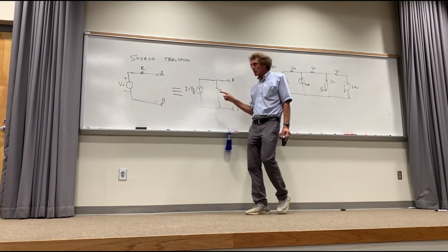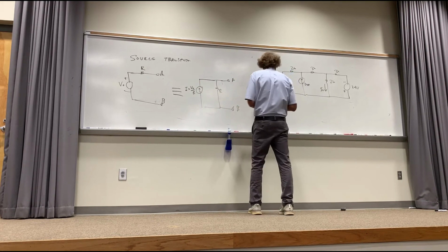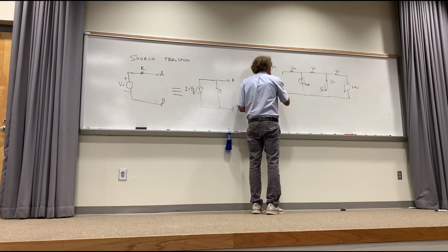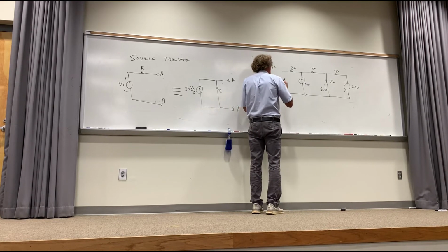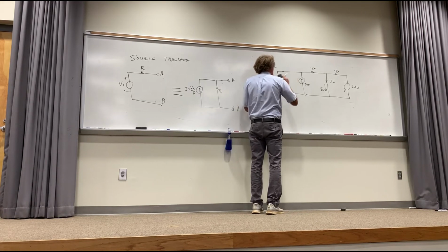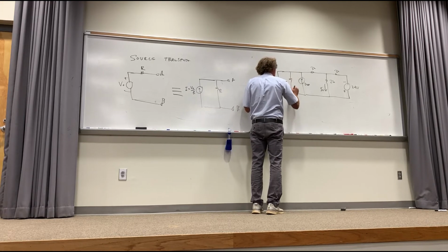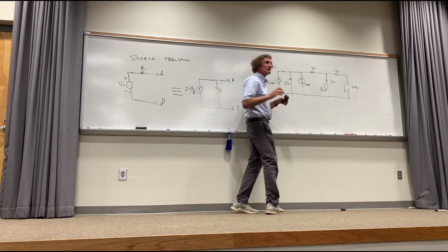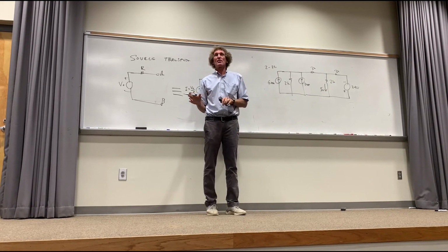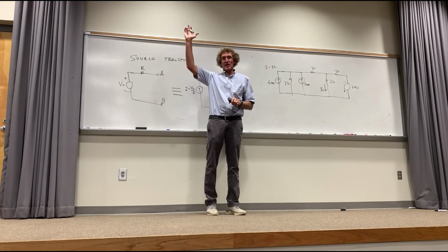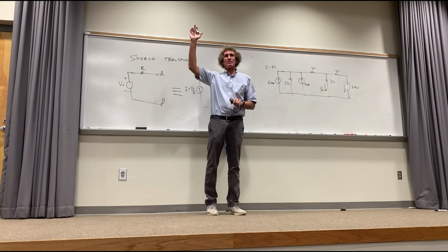All right, so the current source would be 12 divided by 2K, or 6 milliamps, right? So it'd be 6 milliamps, flowing up. And the resistance 2K would then be in parallel here. Can you all see that, class? I've just replaced that source with a parallel version. How many can't see this? You understand what I've done way back there?